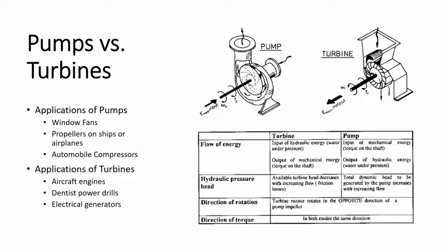Turbo machines can fall under two categories, depending on which direction the generated power is transmitted. When work is done on the fluid to change its momentum and increase its pressure, it's called a pump. Pumps are power-absorbing turbo machines that convert mechanical energy into fluid energy. Shaft torque is exerted by something like a motor and forces the fluid to move, which results in the flowing motion that we commonly associate with pumping.